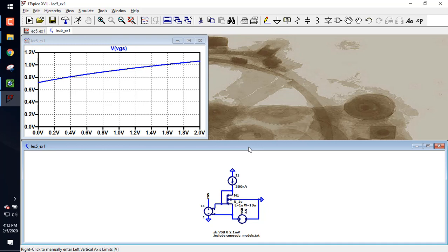All right, what was the other way? If you use 9.12 or 9.13, it says that if the resistance is very high, then VGS will be about equal to VTH. So I just did that. I did it pretty much the same as you, except I didn't put that weird thing on the left. Yep, and then I just measured VGS and it was the same as that. Anybody else do it that way? All right, are we good with this one?